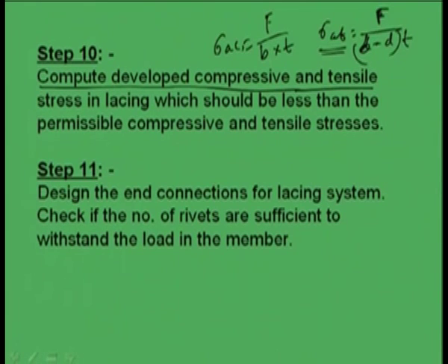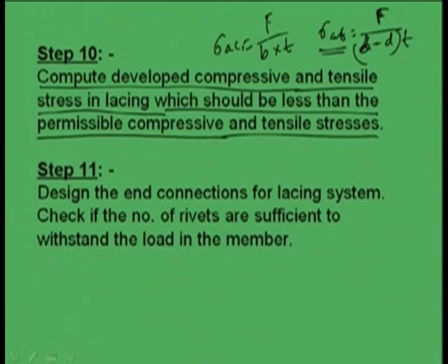So, from this we can find the compressive stress and tensile stress in lacing, which should be less than the permissible compressive and tensile stress.